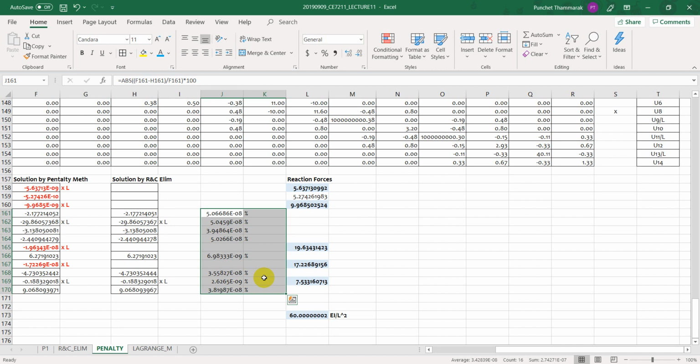And in FEM, in some hot spot like the stress concentration zone, some spot where you apply a point force or a sharp corner, you expect stress concentration. So a fine mesh will be required to pick up an accurate solution. It is not special, it can generally be seen in FEM.